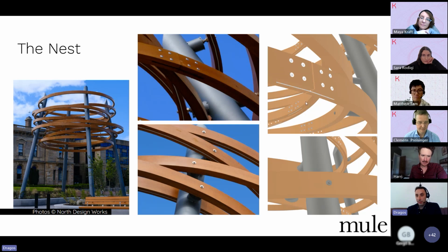And the splice is a moment connection in the vertical plane, or sort of vertically to the plane of the ring, but it's the flexibility of the flitch plate in there and the tolerances allow it to sort of kink around, plus it's timber, right? So it's going to be a little bit flexible. Allows that to work as, you know, we engineered it and we thought about it.